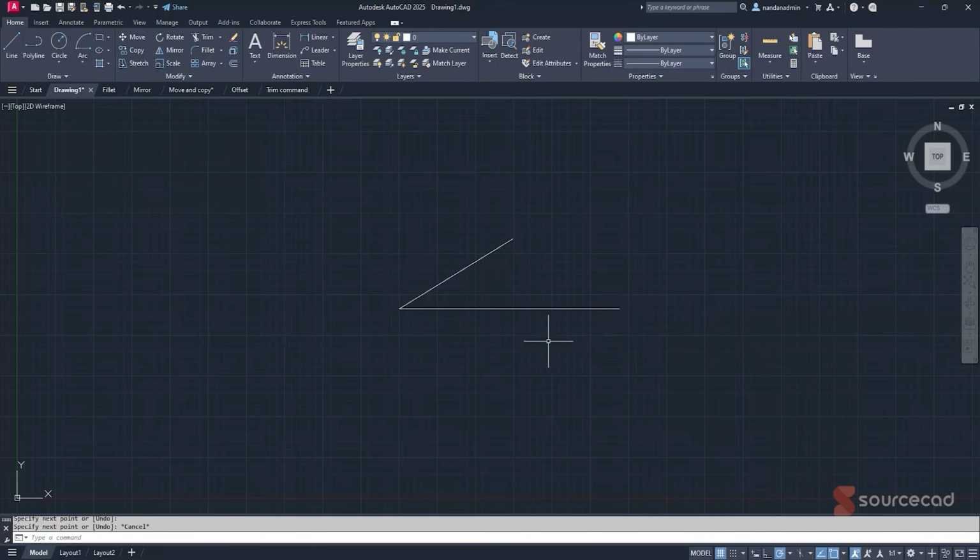So this was the original line, right? Obviously the length is longer here because I want to explain something, but this angle from this to this is 30 degrees. Now what if our line was actually inclined like this? What if it was not horizontal? In that case, the angle measurement will start from this original line again. So the 30-degree angle will be slightly here, and that 30 may not be exactly equal to what AutoCAD would expect. So in AutoCAD, angle is measured from the positive side of the x-axis, but only for the rotate command, angle is measured from the original position of that object.